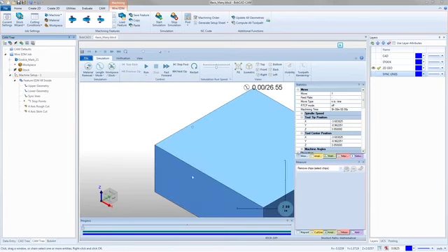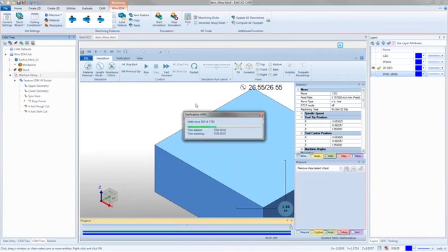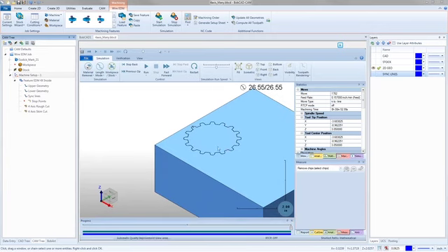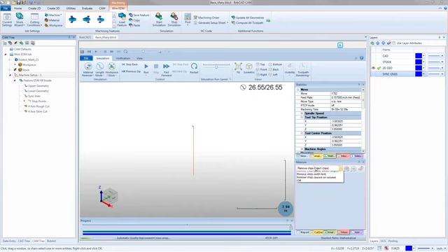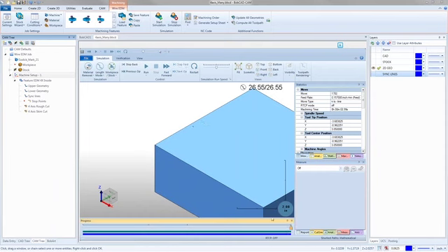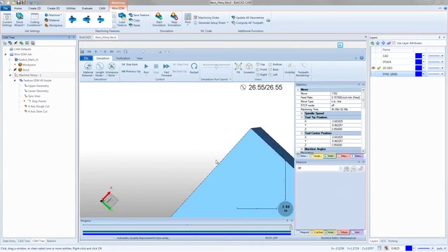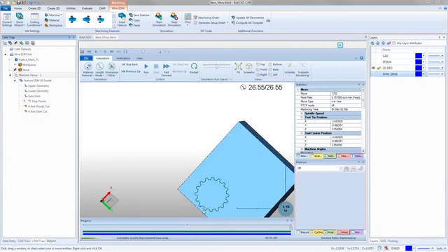Let me restart this, and we're going to look through here and find out if there's an area that didn't get cut. So let me fast forward through it again. And I'm going to try and look at it from the top and the bottom. Hopefully it should be cutting all the way through. Son of a gun, I hit the wrong button to rotate. Just so you guys know, rotating in your simulation is done with your left click, not your middle mouse wheel like you do everywhere else ever. Right here. So rotate. Did I make my stock too thick or what's going on?